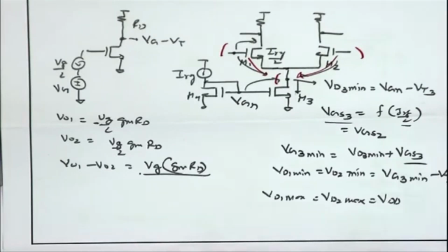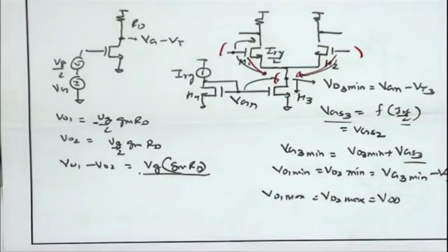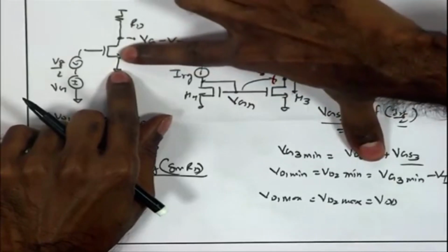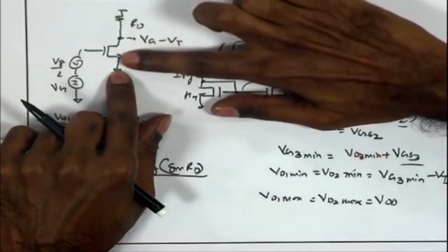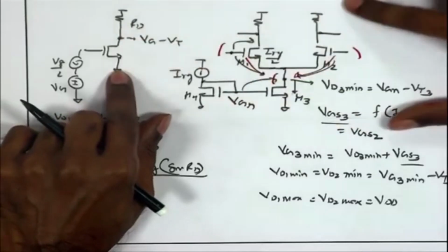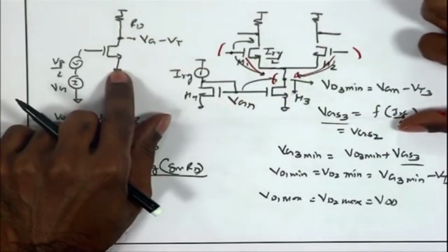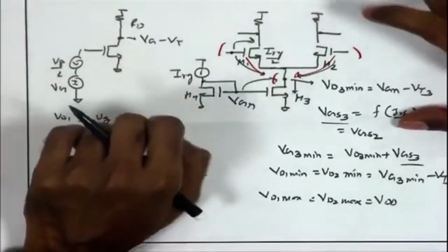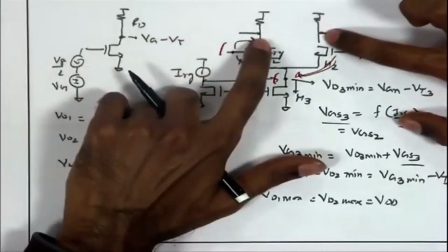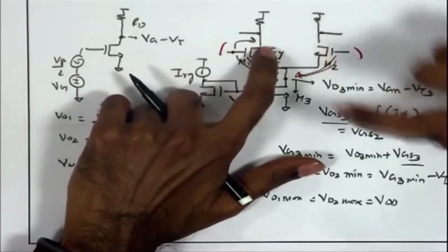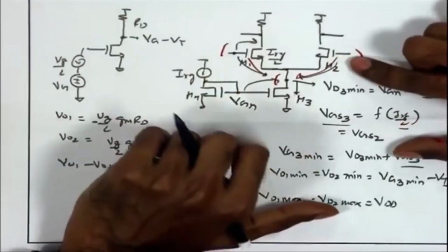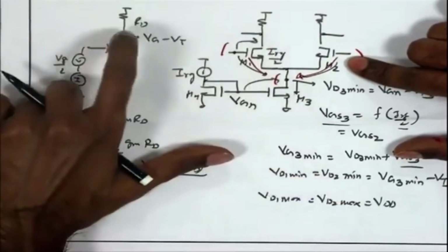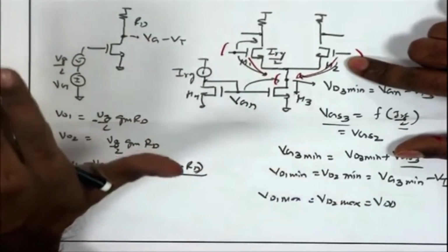What about the noise? Do we need to do something else with the noise? We are talking about the differential operation. What happens to the differential operation if we are talking about the common mode, the noise produced by these transistors? For M1, the effect of noise is going to be similar, and we do a similar analysis. M2 also similar. The only thing we have to take into account is that for noise voltages we do not consider their polarities, we consider their mean square value. So we cannot say that the value here will be Vn1 minus Vn2, it is just the mean square value. We need to look at the mean square noise at this point using the half circuit, which is the same as what we did for common source.